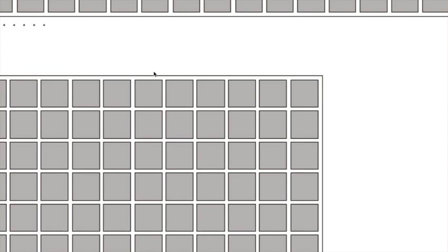It is going to have to be bigger. So I want you to look at this and consider. Let's even do it simple. Let's just say I just want to hit one pixel, but it's got to illuminate one complete pixel. A partial illumination of a pixel is no good. I need at least one pixel fully illuminated. And I don't know where the light is going to fall in this array. It can fall anywhere, right? So look at that and tell me, how big do I have to make that to guarantee that one pixel will get fully illuminated? How big does the circle have to be?